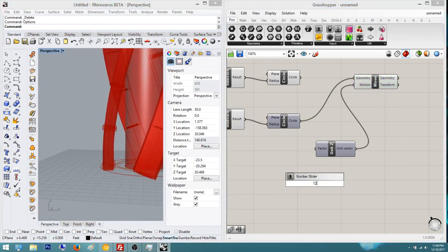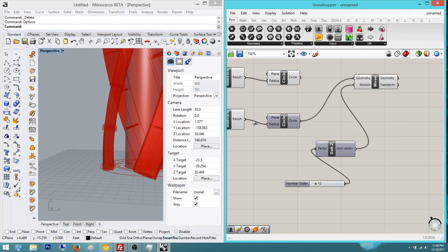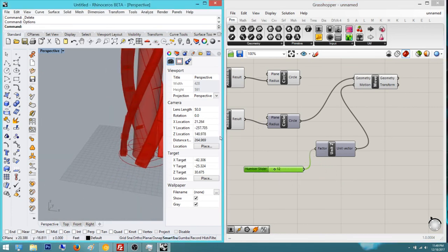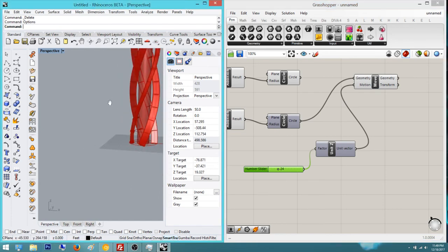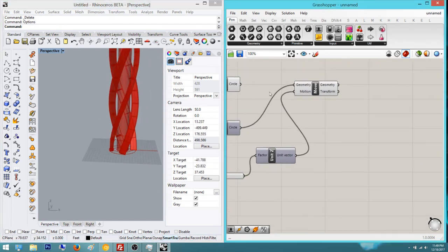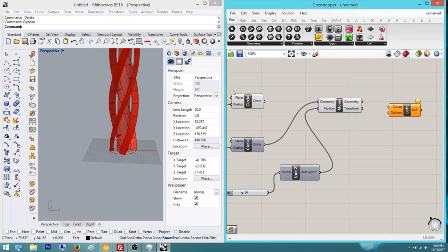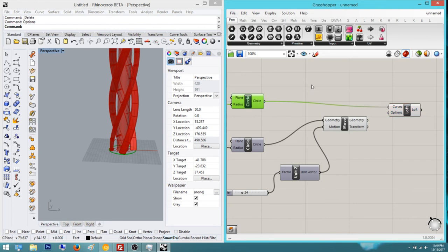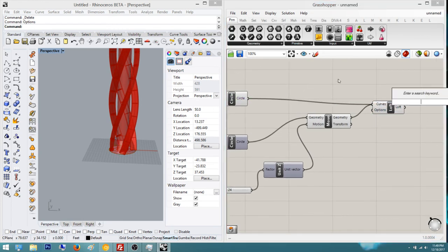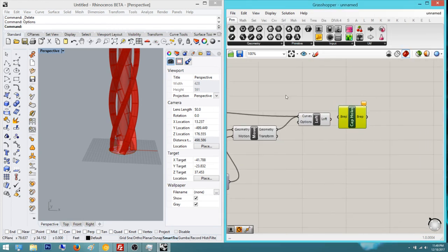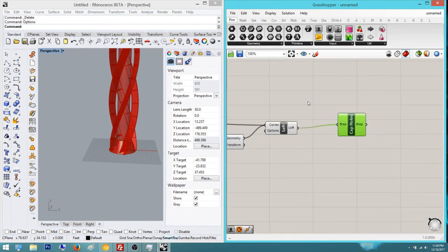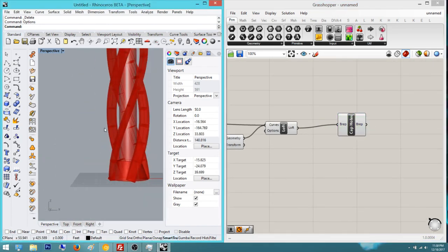I turn this off first, move it in the z-axis, and actually start to get some depth on this. So let's move it 12 so far. Let's make it a little higher. Yeah, like this. That's perfect. 24 feet. And now all we need to do is loft those two to create that base. So 1, 2, and then cap holes. We got it. Boom. Done. So we cap the holes, and we have that base now.